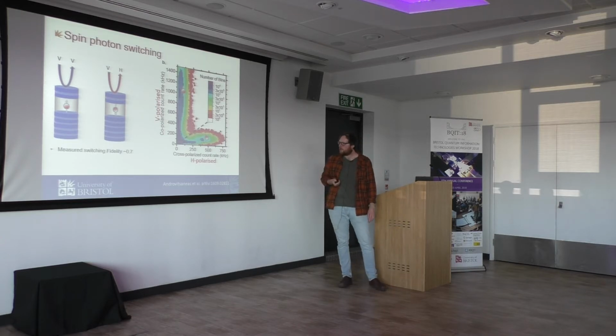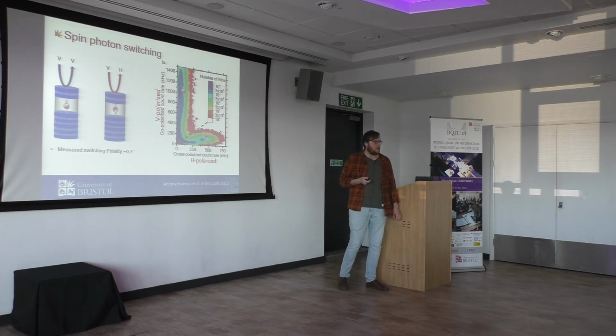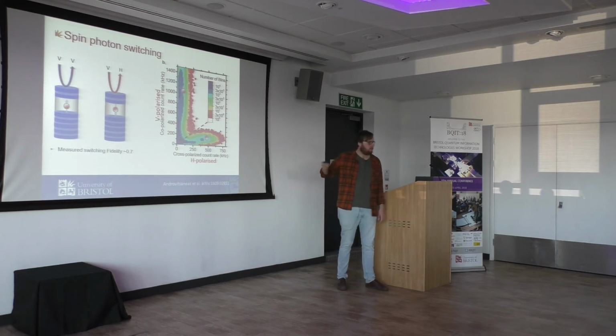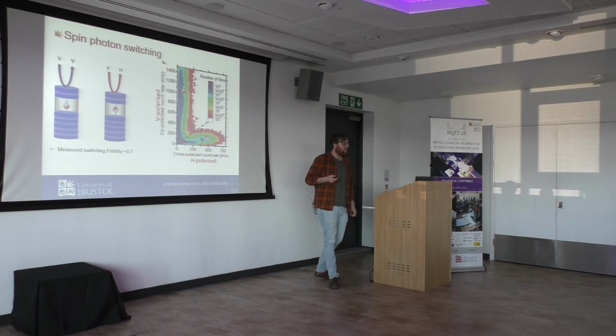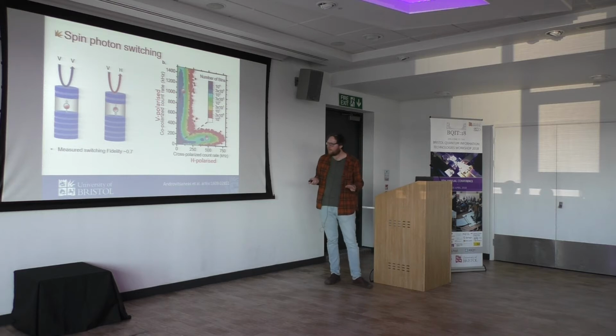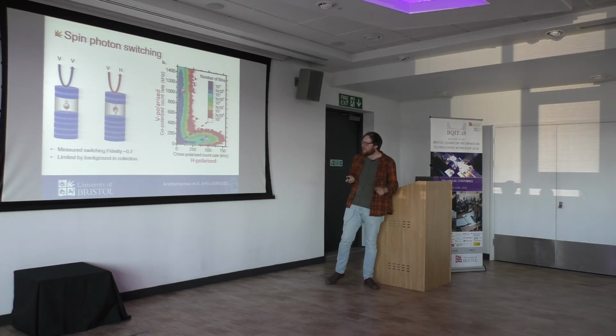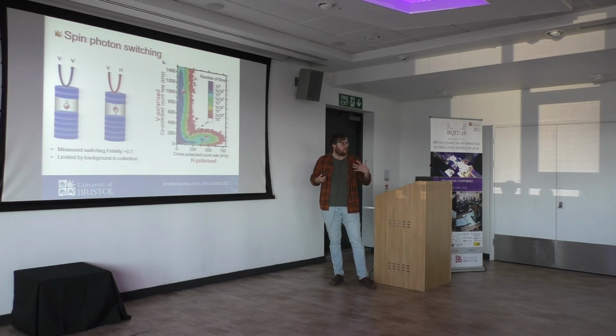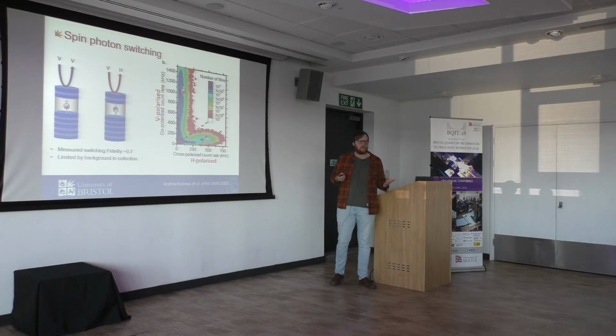From this measurement we can calculate a switching fidelity of around 0.7, which doesn't sound that impressive after all the previous talks talking about 99% fidelity. But actually that's significantly higher than anyone's ever reported in the past. And importantly, it is not intrinsically limited by the device itself, it's limited by the collection efficiency, so the mode match between our micropillar mode and our external optics.